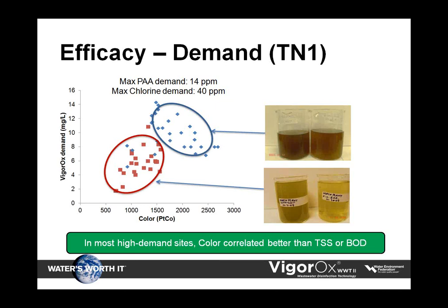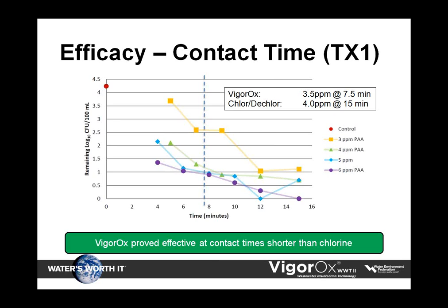So let's review now how contact time impacts PAA disinfection. Many studies have shown that PAA can achieve the same disinfection performance as chlorine at shorter contact times. This can be critical for plants that have to spend on new contact channels. This was the case for a plant in Texas.